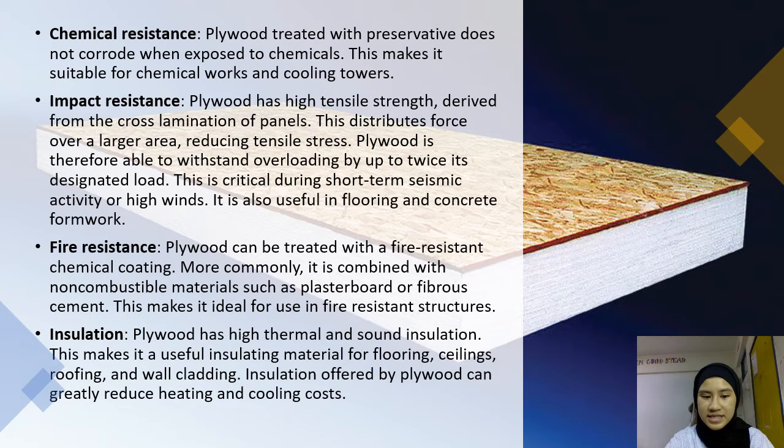Fire resistance. Plywood can be treated with a fire-resistant chemical coating. More commonly, it is combined with non-combustible materials such as plasterboard or fibrous cement. This makes it ideal for use in fire-resistant structures.